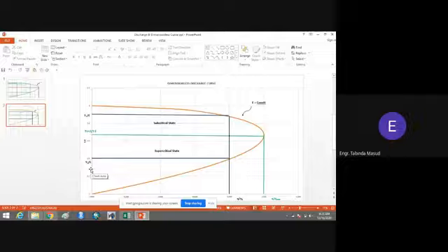E is already known to you. E here and here is constant. Why? Because the whole curve is for the constant specific energy head. So if you also have this value of the energy, then you can find the alternate depth of the flow. This will be quite clear when we solve the numerical problems, because you have to solve them on the basis of the dimensionless discharge curve, and you will come to know it clearly.